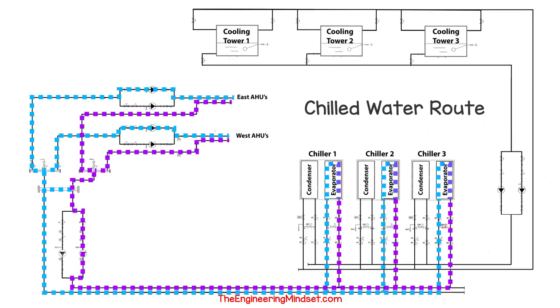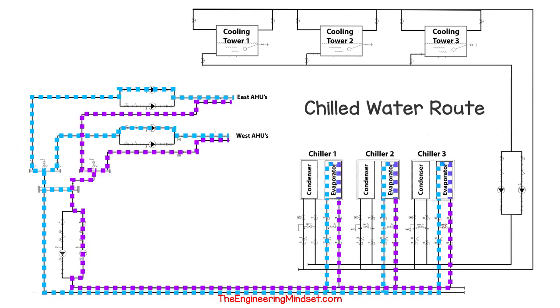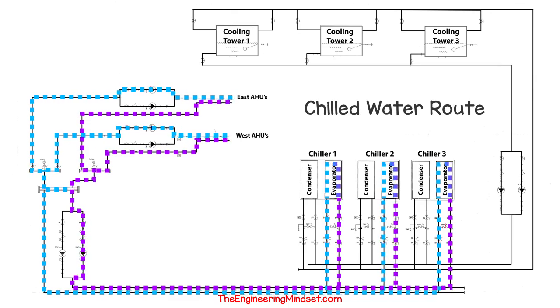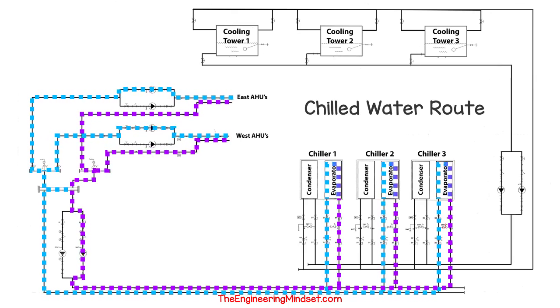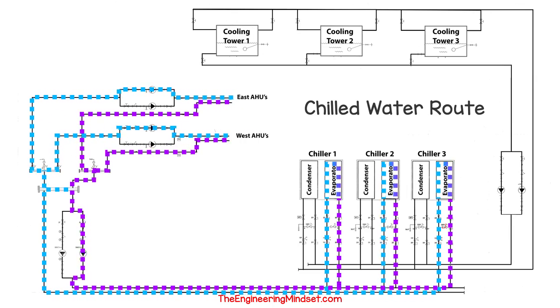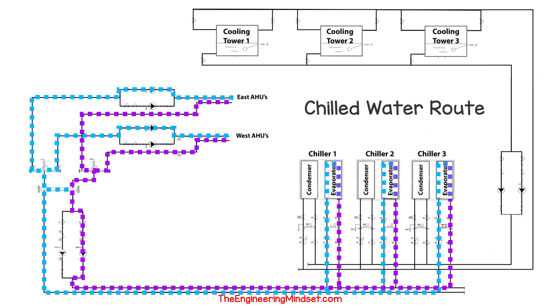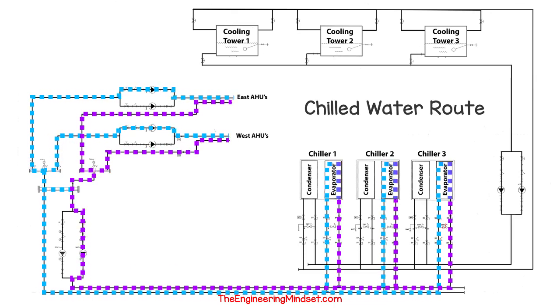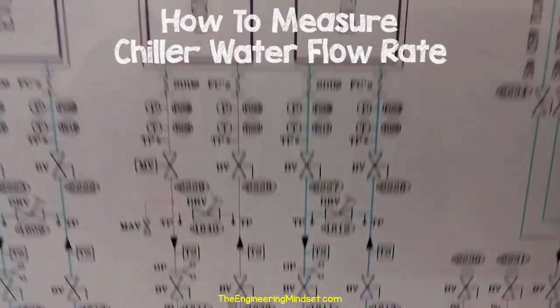Now also notice that only one of the 2 pumps is running in each pump set. This is because they are using duty and standby configuration where a pump is made the leader and will run while the other pump acts as a backup just in case the leader pump fails. Now these roles are reversed every so often just to keep the run hours similar, and this will usually reverse every week or so. So let's look at a real world example.